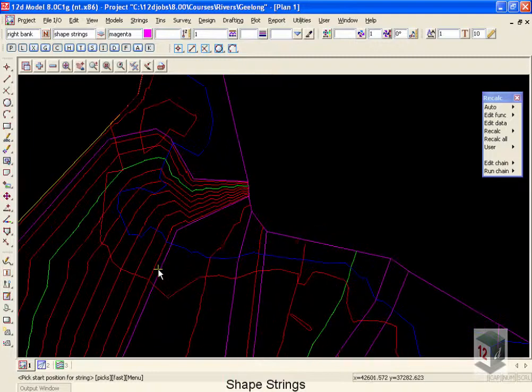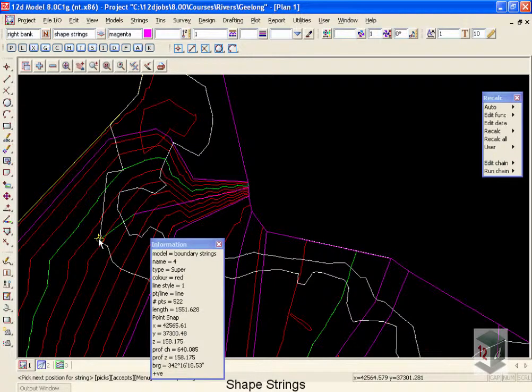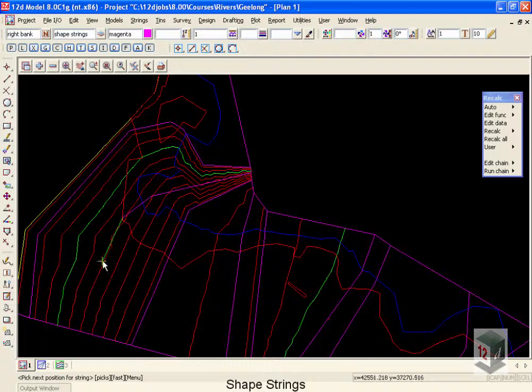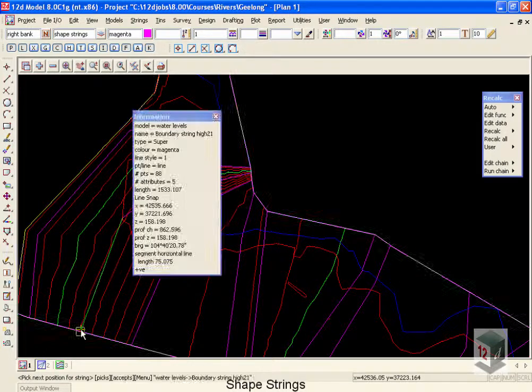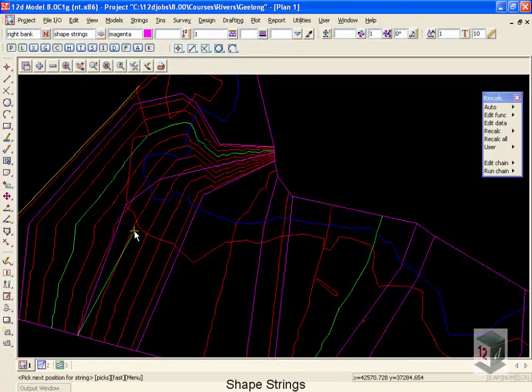And the idea here is that everything's looking good inside this area, but it's inside this reach when the water should be starting to turn and flow perpendicular to the river. So if I'm looking through this reach here, I would expect that a cross-sectional perpendicular line would come about this pattern. So I'm going to start mine about there, bring it into where I expect it to be perpendicular to the flow, so across there. And then in this area, I'm happy with the way that's going perpendicular out there, so bringing that all the way across.